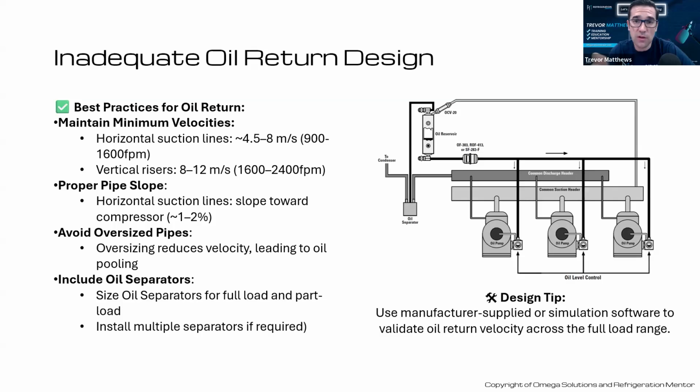Because when you're designing the oil management, there's 5 or 6 different designs you can do, which we talk about in the program. And so you want to understand when that oil transfer solenoid opens up, if that's the design you use, that needs to make sure you're moving enough oil into those compressors. And then those compressors have a certain amount of carryover. You've got to understand all that stuff